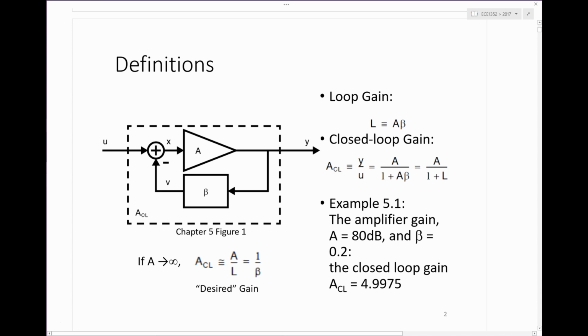So you're probably familiar with this picture of negative feedback, where there's an amplifier with a forward gain of A, and then a feedback network with response B, or beta. We define the loop gain. So this is a bit of naming we have to be careful about. The loop gain, or also called the open loop gain, or more appropriately, the loop response, or open loop response, because of course in general it's frequency dependent. That is what you get by going around the loop, right? So in this picture, that's simply A times beta.